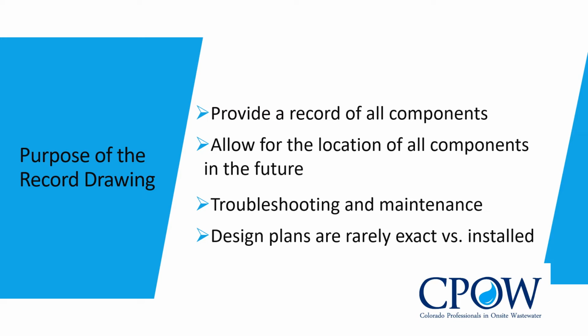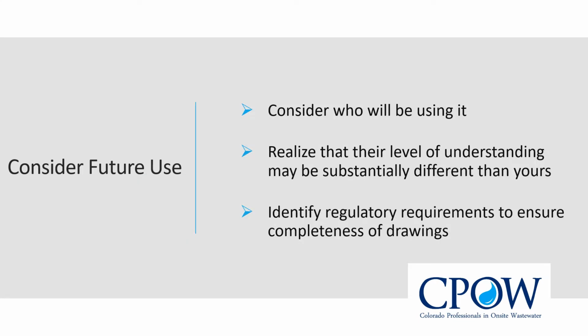Note that due to a variety of reasons, systems are rarely installed at the exact location and elevation proposed. When creating record drawings, consider the person that may be using it in the future, a future homeowner, pumper, a regulator, or an O&M provider. Remember that each of these persons of interest may have a significantly different level of understanding of how an OWTS is constructed and functions. It's also best to check local agency requirements. Certain counties may have additional requirements or require the drawing to be submitted on their form or in a specific format.